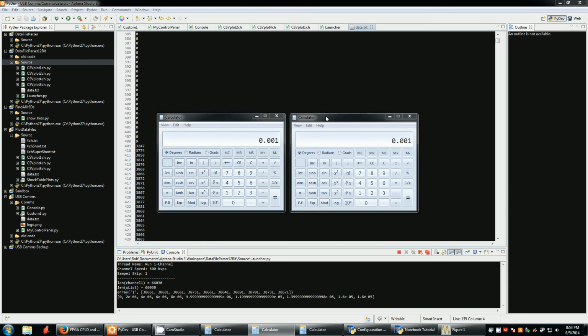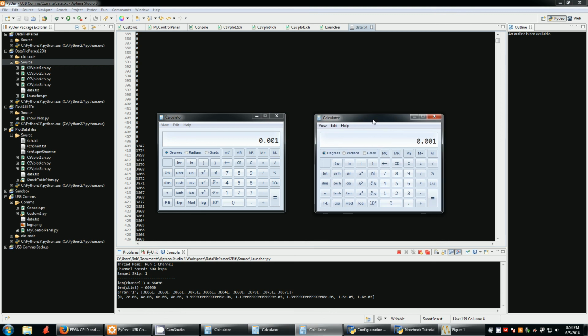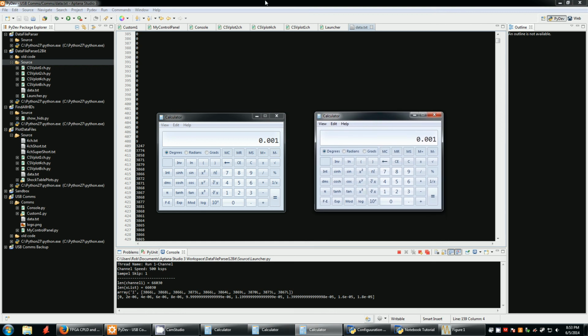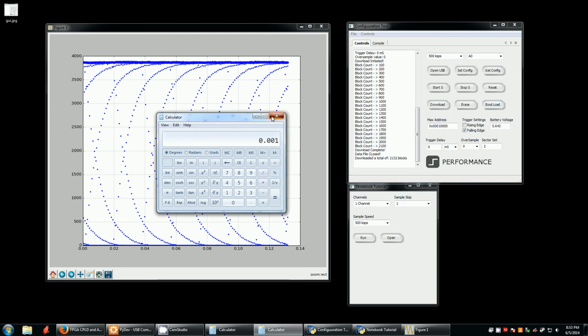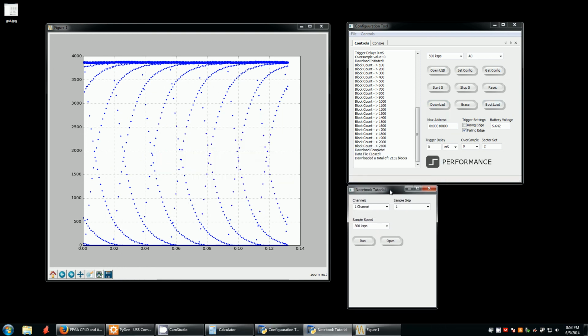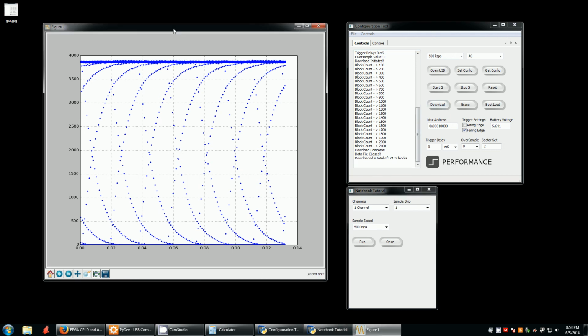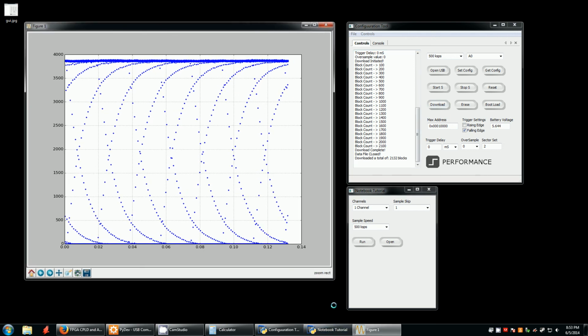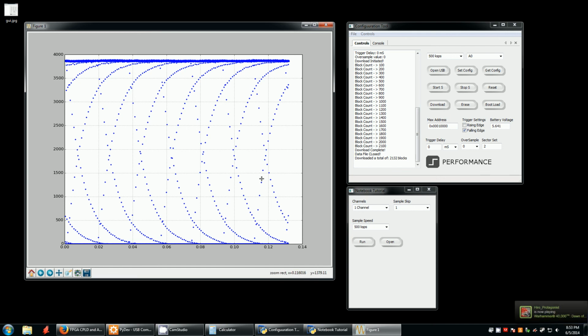I've got a demonstration to prove out data integrity. It's with 4 channels, and I'll probably have data integrity demonstrations for every channel. And so go to the website to check that out. It's basically some custom firmware that pushes a counter into the memory space so that you can see a sequential step through memory, pull that data back out, and then use some of my custom tools to check that data file. And if you want the source code to check that out, you can feel free to let me know, and I can put the source code up, link it, just so you can go through it and make sure that you're comfortable with that. It's a pretty robust integrity check.